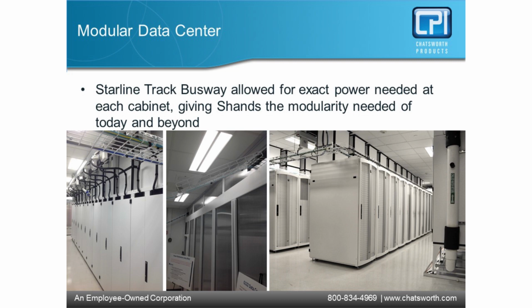One of the other questions that came up, poll questions, and I think it's important to just touch on this quickly, is the arc flash and performing live work. When you're evaluating a busway, one of the main items you want to take into consideration is, is this bus listed as hot pluggable? There's a UL standard for busway products. It's actually 857. And our products are all tested and meet the requirement for live insertion. So there's a listing component of this.